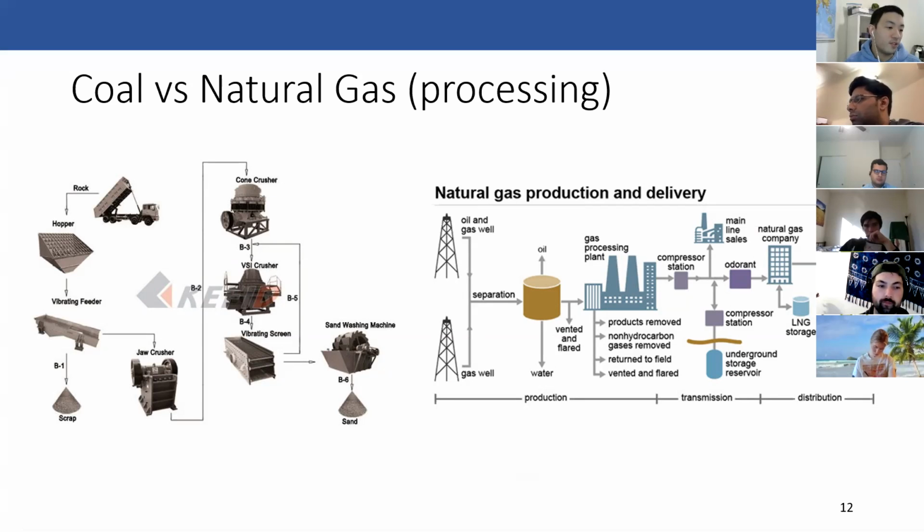it has a little bit of filtering, but mainly to remove scrap that's not really combustible. And then all of that fuel goes through a number of crushers and millers that will grind the coal down into fine particles for combustion. Okay, and the reason why you do that is it makes for more efficient combustion, because the finer the particles, the more surface area you have to work with for the combustion process.